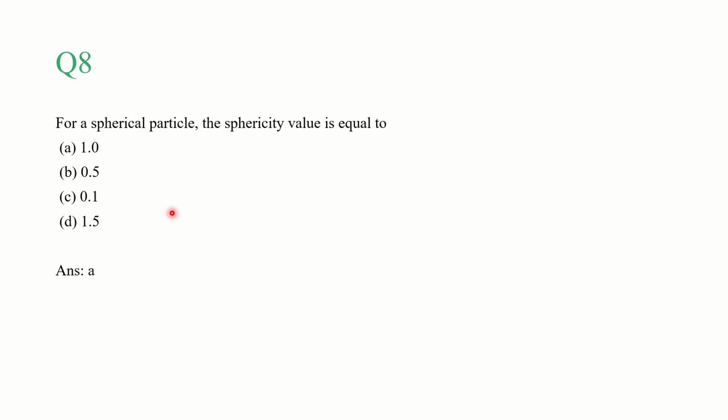But studying them using models is not an easy task, to represent the irregular nature of the particles. So the easiest way would be to go with the sphericity associated with the non-spherical particles. We put the sphericity of those non-spherical particles into the model of the spherical particles, and we can study them. That would be an approximate way, but it is not the exact way. So studies are being conducted to identify the exact way to model those non-spherical particles, but they are still in progress, right? So sphericity is one such concept to study the irregular shape of the particles.